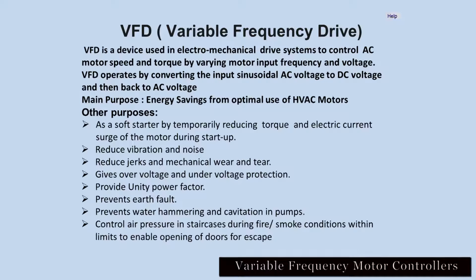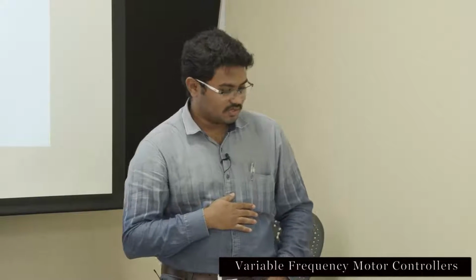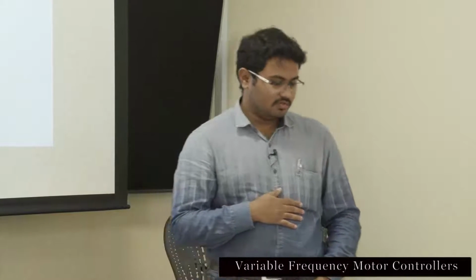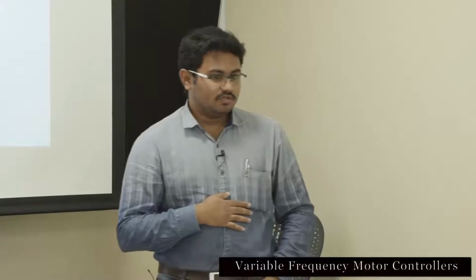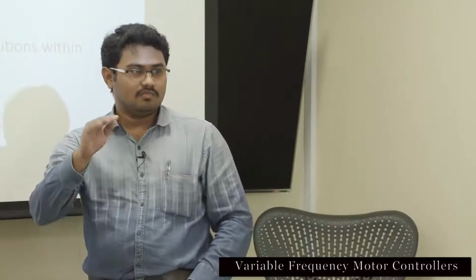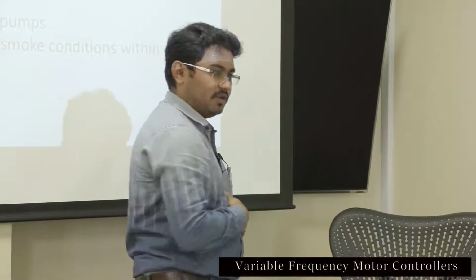And then it has all the protections like under voltage, over voltage, motor stall function, and the drive overload function, and you can decide your own user overload for the applications. So those things can be configured in the drive, and it can prevent the faults which are happening in the motor. And due to the configuration, we can increase and decrease the acceleration time and the deceleration time of the motor. We can avoid a hammering effect on the pipelines.